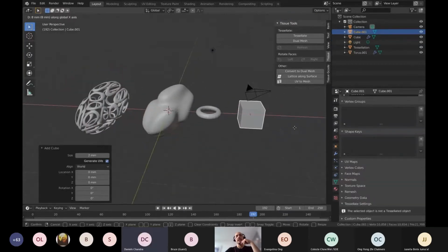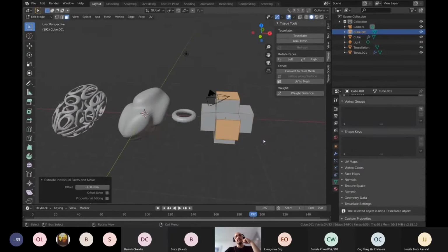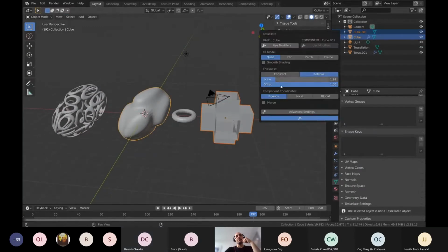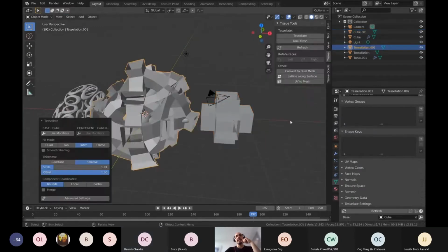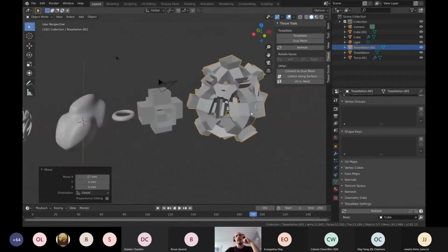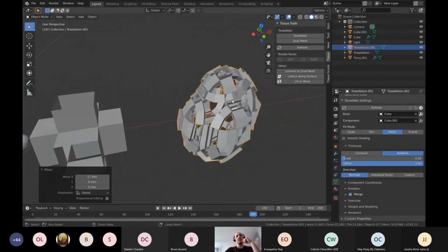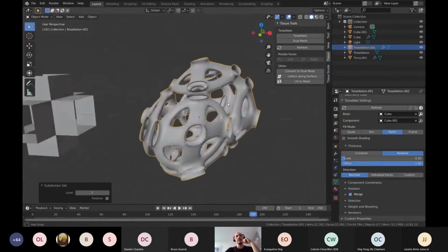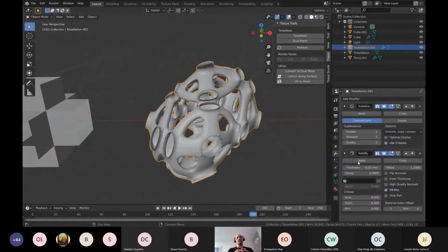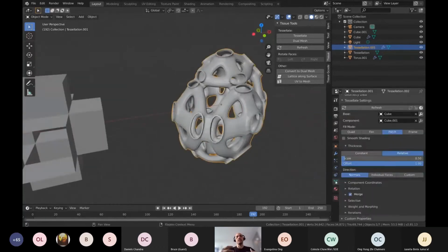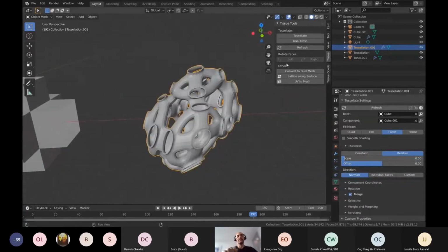There are many different techniques, but in general they are always based on the same principle: you have a geometry that can be multiplied according to another geometry. Usually this is based on the individual faces, but sometimes there are also methods that allow you to work on a portion of the surface, creating a smoother deformation of a component according to that part of the surface.